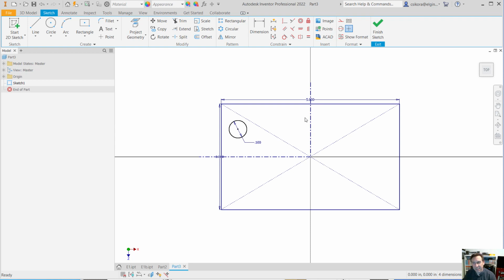Now it's easy to fix. You just click on whenever you've made a center line and turn that off, and it will return it back to normal. So it's not a big deal. But let's go ahead and position this now. So let's go to Dimension, and it gets positioned 0.75 off this edge. And again, center point to left edge, 0.75.